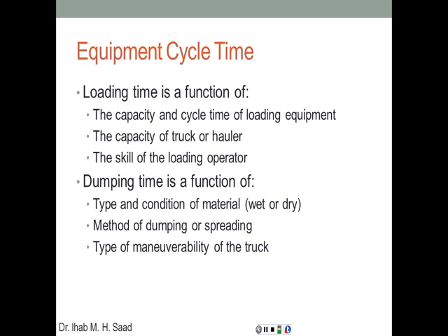The larger that angle of swing, the longer it's going to take, which means the cycle time is going to be longer. Whether it's dumping on the ground or in a truck, whether the truck is a large truck or a small truck, how skilled the truck driver is, how big the bucket of the loading equipment is, and how big the bed of the truck is where you're going to be dumping the soil. All of these are elements that affect the loading time.